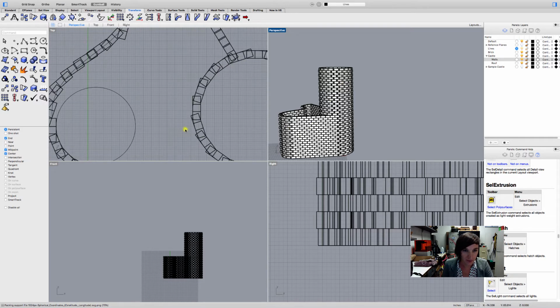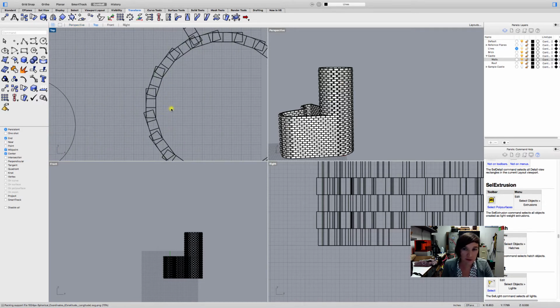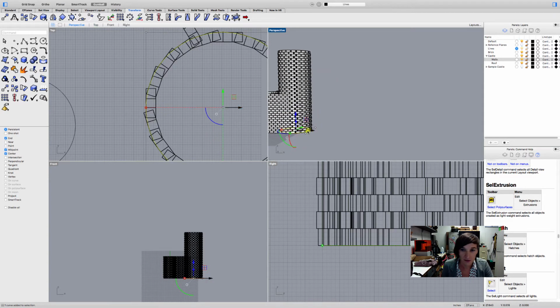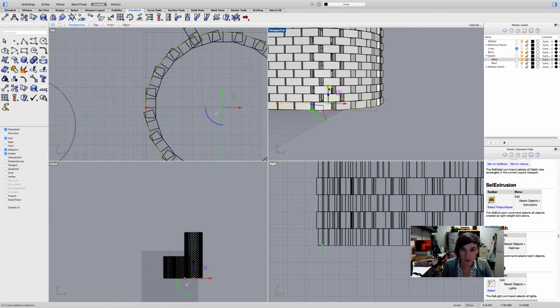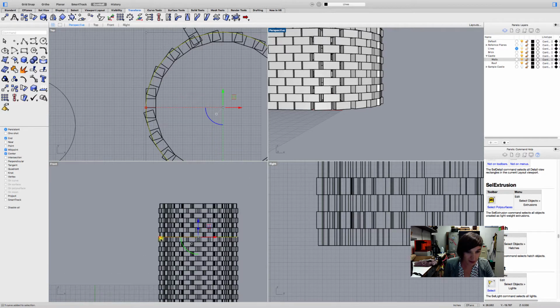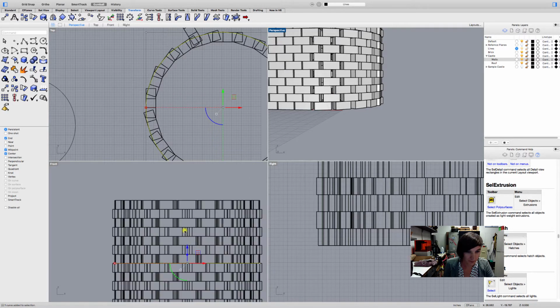It'll be really cool. The first thing I'm going to do is move this circle up. I'm going to use my gumball command because it's a simple movement, and I want it to relatively stay where it is. So I'm going to hit the blue arrow, and it's going to ask how far to move it. Now each block is 1 inch thick. Why don't we move it 35? Oh, it's all right. Let's move it down by like 4. So we'll hit that again, and I'll say -4.